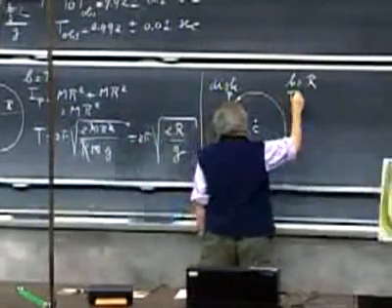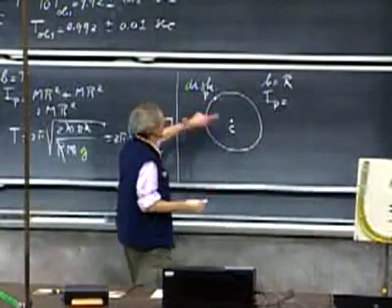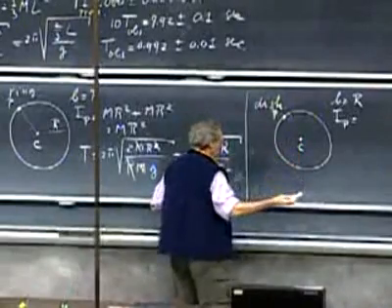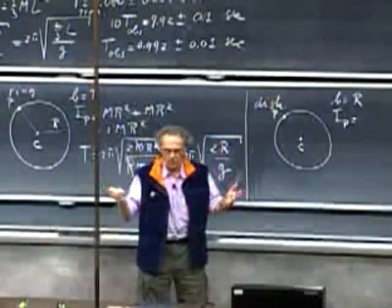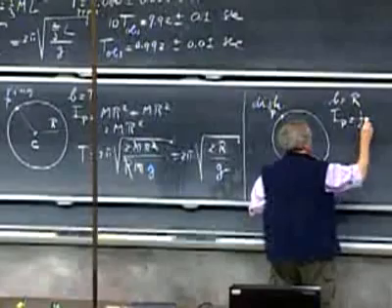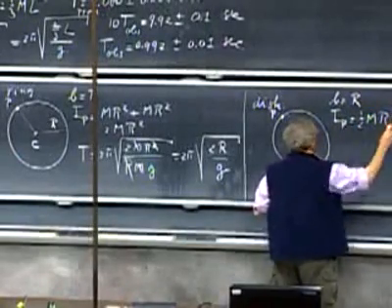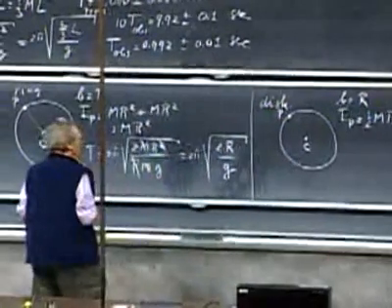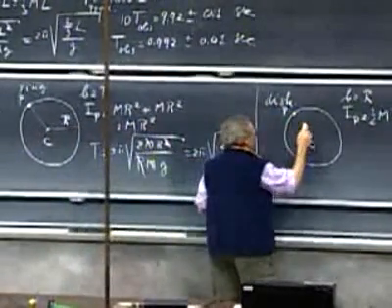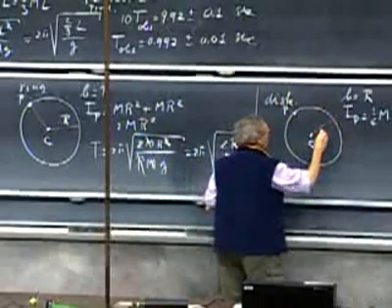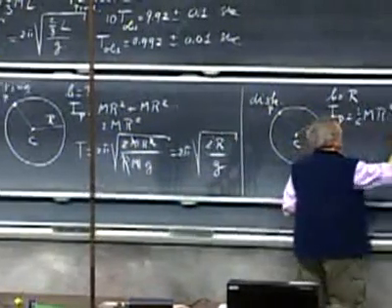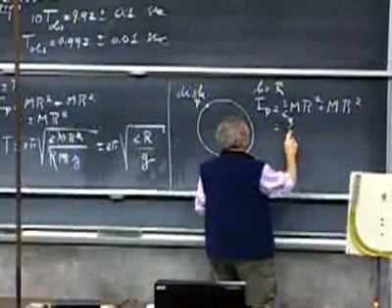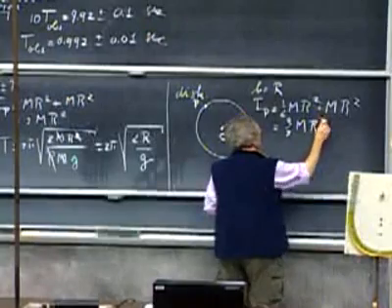And the moment of inertia for rotation about point P is now the moment of inertia for rotation about the center of mass, which you look up in a table. In the case of your exam, it was given on the front cover. 1/2 m r squared. That's the moment of inertia for rotation about the center of mass. And now we have to add m b squared and B equals R, so we have to add mr squared. So we find 3/2 mr squared.